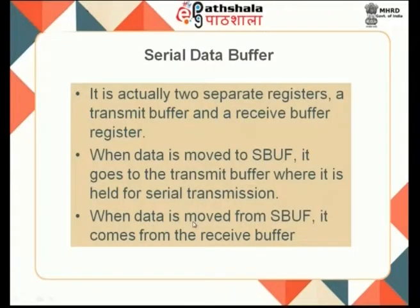Then the next important thing which we will be looking at is your serial data buffer. That means, if I am looking at serial communication where the 8-bit data will be processed in the 8051 processor, and we are using an input device that sends data serially, that means 1 bit after 1 bit, then I need to provide an interface. In the same way, if I am looking at an output device which reads only the data a bit after bit, then I need to provide a facility for that.